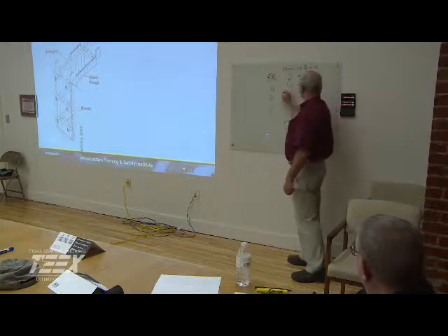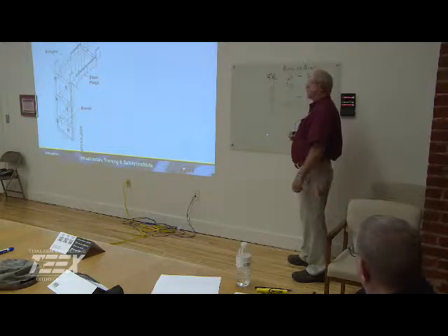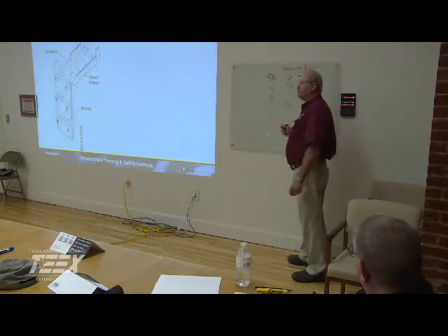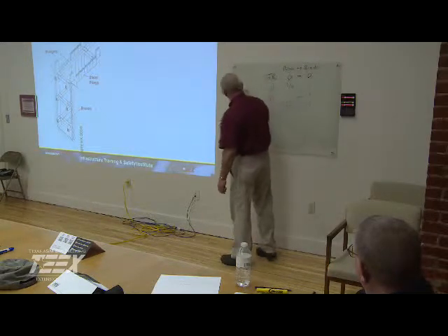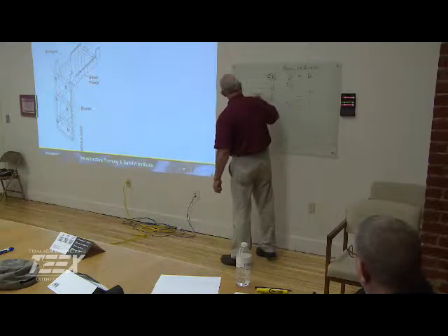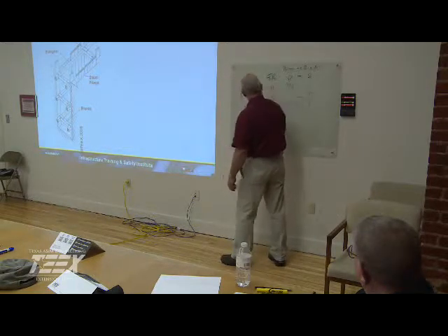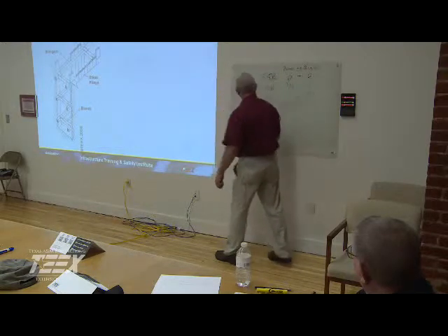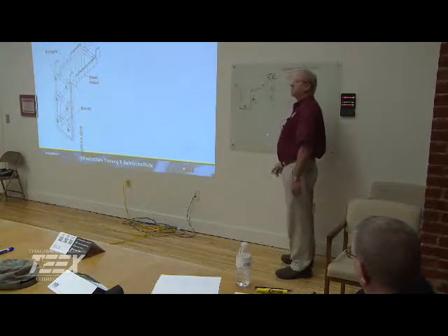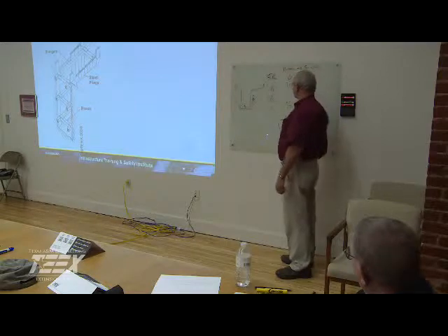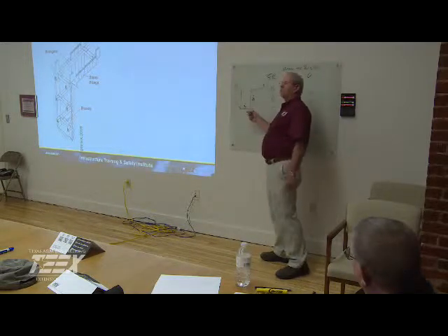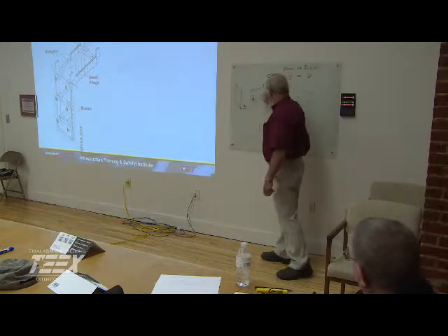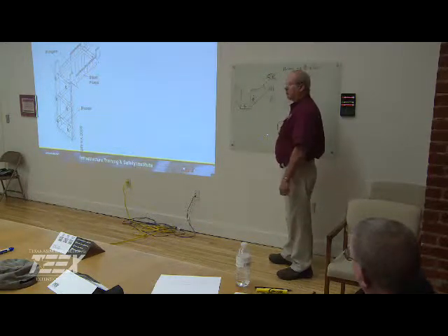So most soils are classified B. In Texas, most of them are B. So if I have a trench that is, say, 10 feet deep and 3 feet wide, then I'm going to slope back 10 feet, 1 to 1, 10 feet, and that is to help protect the person, okay? And you can use shoring, you can use benching, but this is known as the maximum allowable slope.